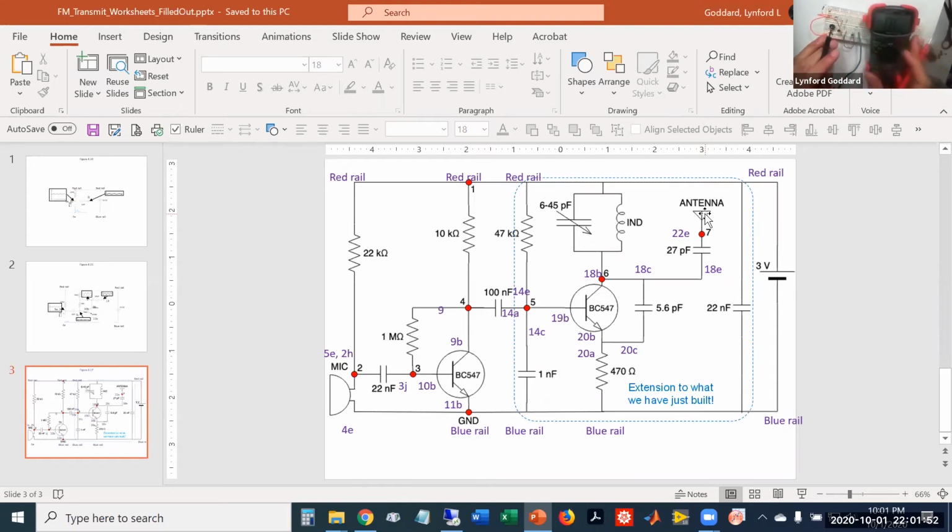So what I want to see is if I touch one end, it doesn't matter red or black, I'm making contact between the other end of the antenna and the red. And then I want to probe and just see, well, if I probe the wire, of course it's going to beep, but I want to see it's electrically connected to the pin. So if I probe the other leg of the capacitor, I can see that, yes, this is properly plugged in.